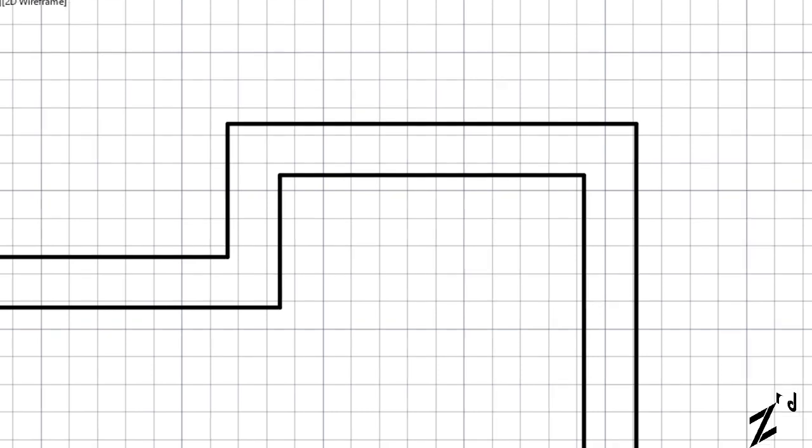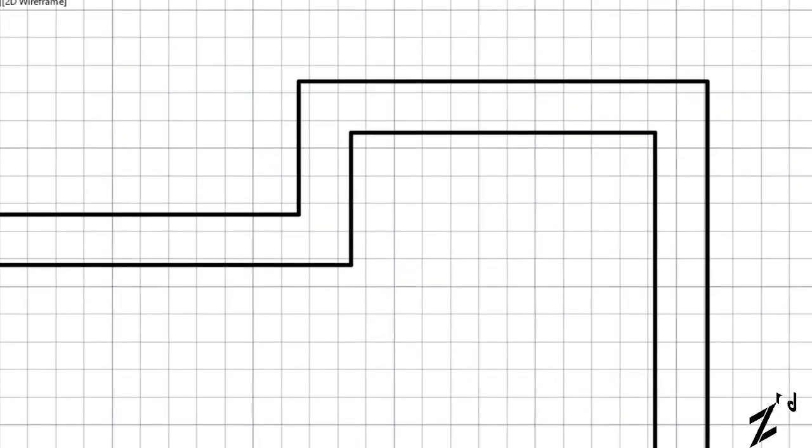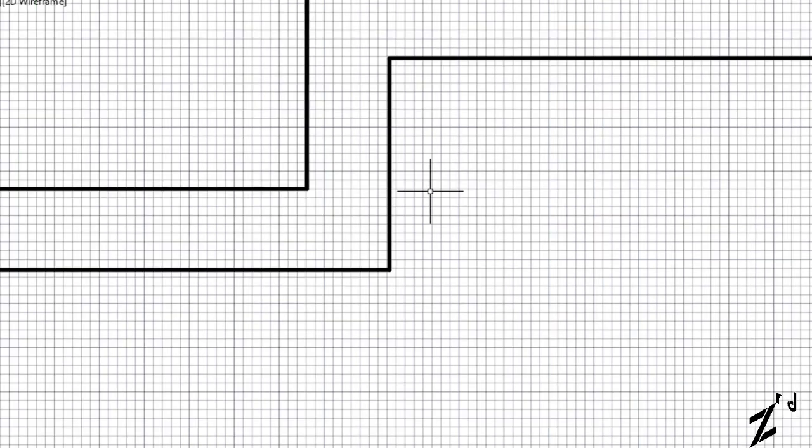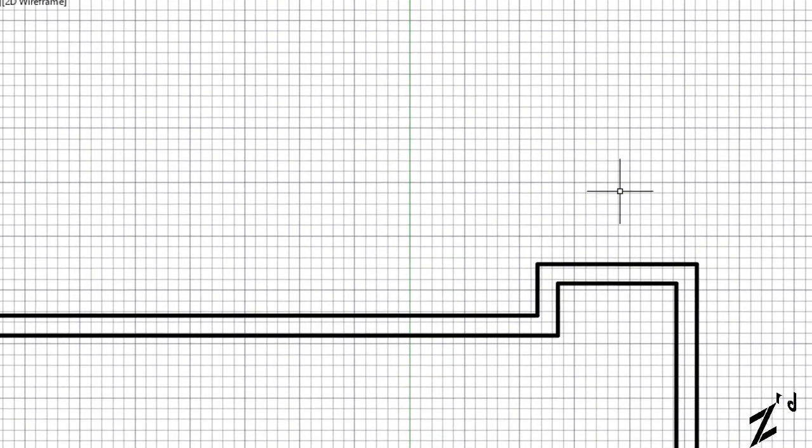Okay. So, we were talking about the materials that are used for wardrobes, which are your 6 mm, 12 mm, and 19 mm plies. There are different grades of plies, but we'll deal with that when we're talking about kitchens. For now, we don't care. With these thicknesses of plywood, we have a few different pieces that we need: the shelves, obviously, and a backing panel, but the most important thing we are going to be dealing with is the doors. The door is by far the most important design factor of this particular wardrobe.